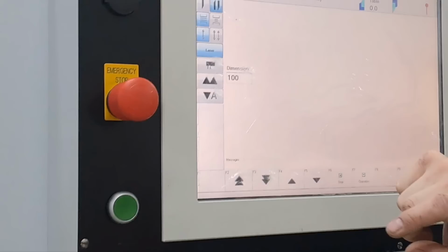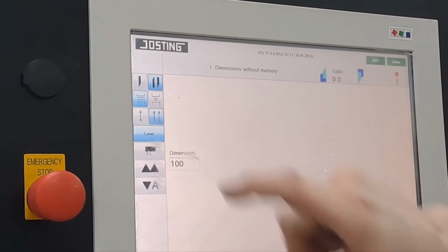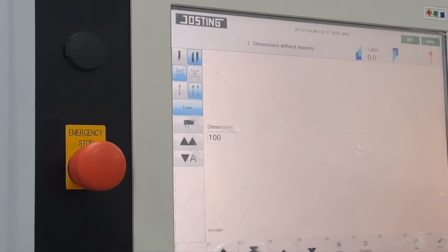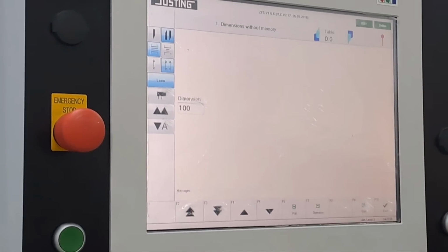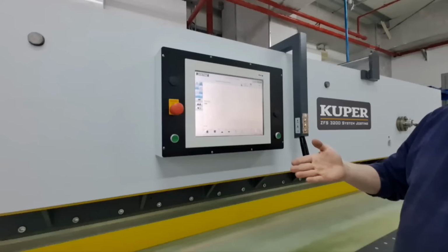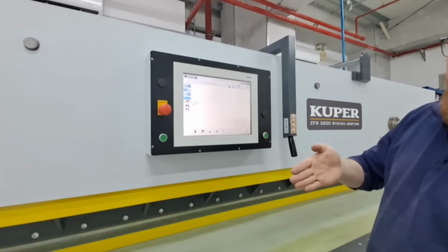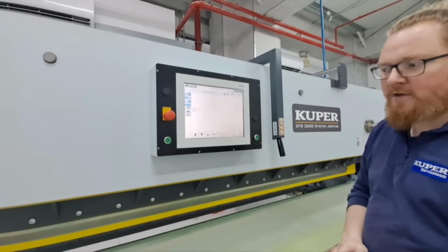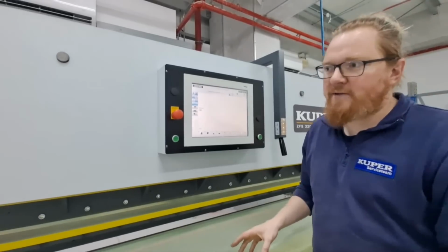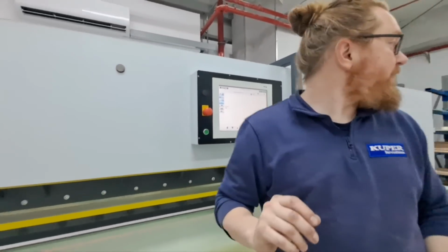The high pressure. This here is like a double cut, so when we start the automatic again, the knife will go to the front, make a cut, readjust by a tenth of a millimeter, and then cut again. So when we put veneer inside the machine, you can see it a little bit better.